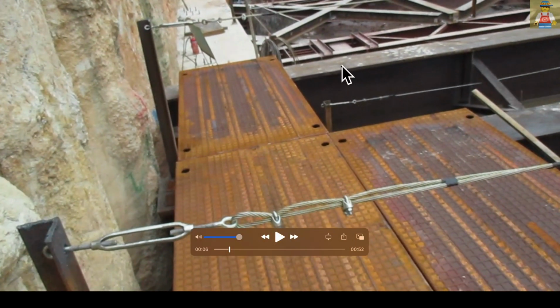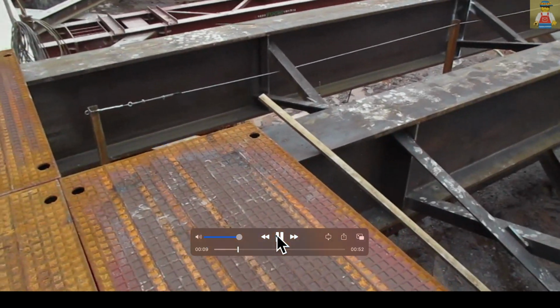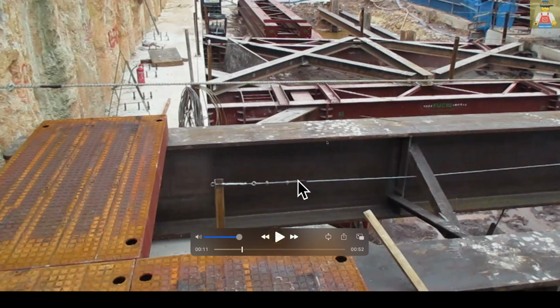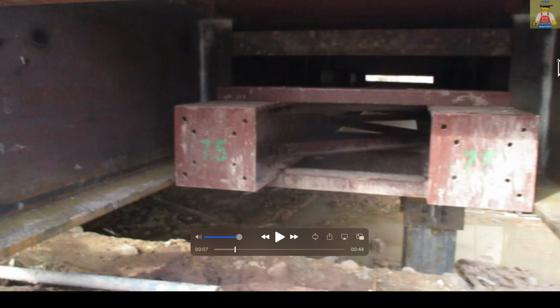This one shows the deck plate and the secondary beam of the decking system. And this is a strut. So if there is a utility below, we install the utility support every 2 meter, hang down angles, decking support beam every 2 meter, and a deck plate on top.